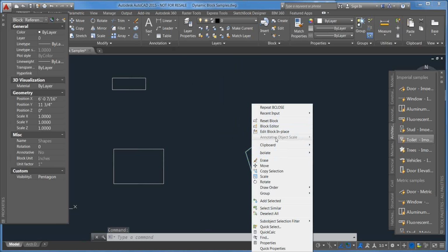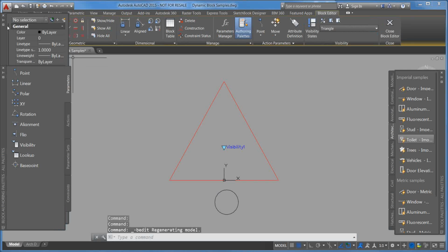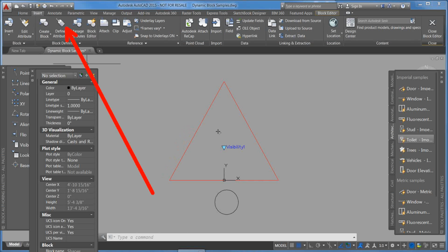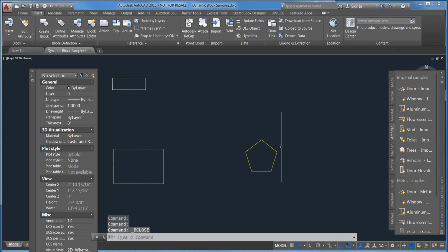And I'm trying to remember if we've done an attributes. I think I did an attributes webinar. I do remember that. It's probably in our archives on our website. Basically here inside the block editor you'll find a, why am I not seeing it? I might have to, do I have to go to the insert? Yeah, I think I have to define attributes here inside the block. So the text, editable text inside of a block is called an attribute. So that's the term that you want to investigate if you're just kind of new to authoring blocks and authoring blocks with editable and dynamic text.